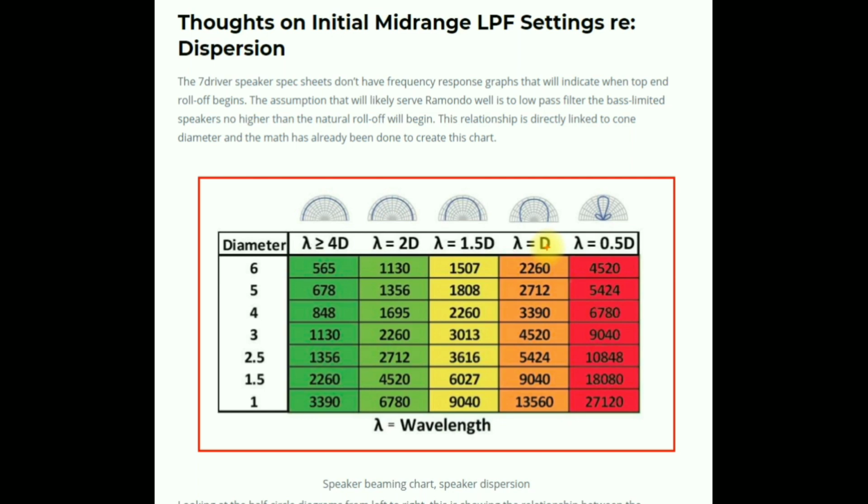So why doesn't everybody build a 5-way system if that's so potentially beneficial for sound quality? Well, it's better to try to keep it simple. The more speakers, the more active channels you add into the system, the harder it is to do the wiring properly. You have more amplifiers you have to fit in the vehicle.